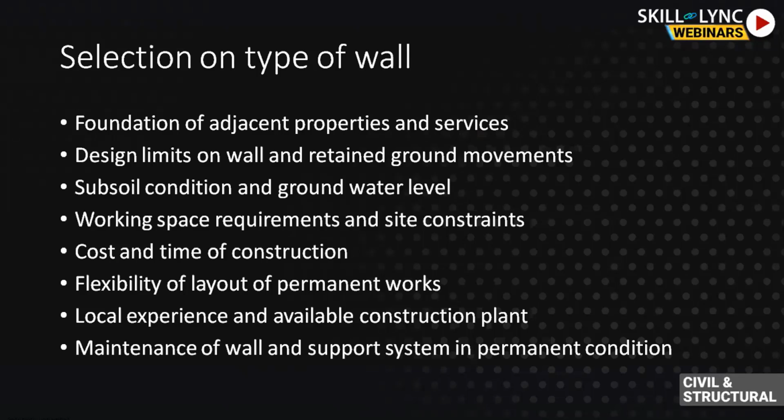Before selecting a wall, certain things are to be understood, like the foundations of adjacent properties and services. So when we are going for underground construction, we should know what properties are nearby. What piles or other structures, foundation footings are nearby, so that we shouldn't affect the nearby constructions.